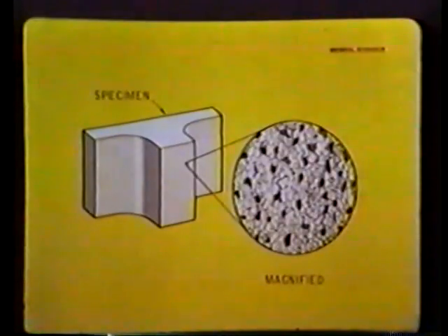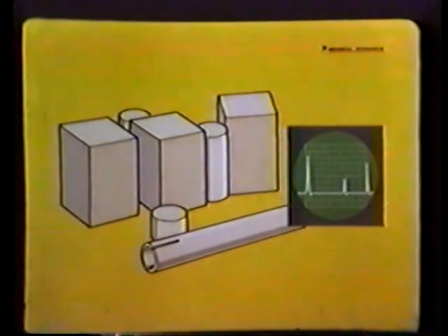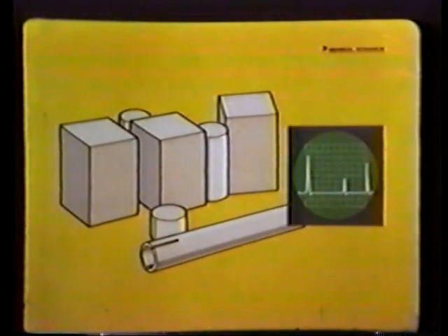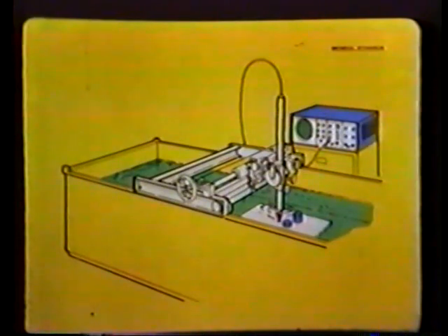Ultrasonic testing demands that you have a knowledge of a test specimen's material, construction, and a clear definition of tests to be performed. There must be adequate reference standards for making comparisons, good test procedures, realistic acceptance standards. And last but not least, the equipment must be calibrated, standardized.